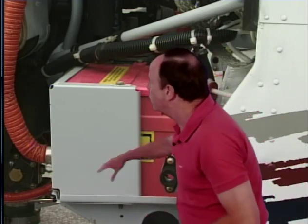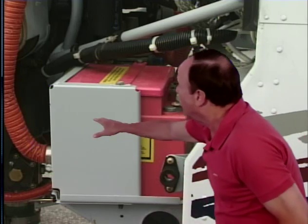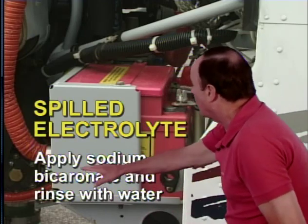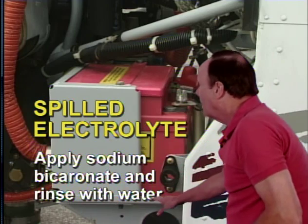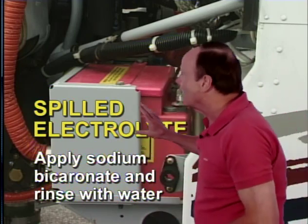And what you want to do is neutralize it with an alkali. The electrolyte is very acid. You want to neutralize it with an alkali, so you'd use something like sodium bicarbonate, because that's an alkali. So you'd apply sodium bicarbonate, and then, of course, you wouldn't want to leave that lying around the aircraft, so then you'd rinse it with water. The best thing is, don't spill the electrolyte. The owner will not like it.